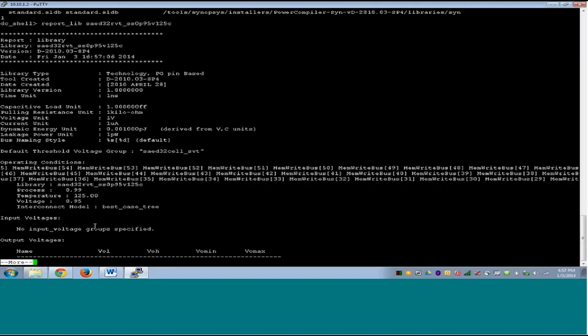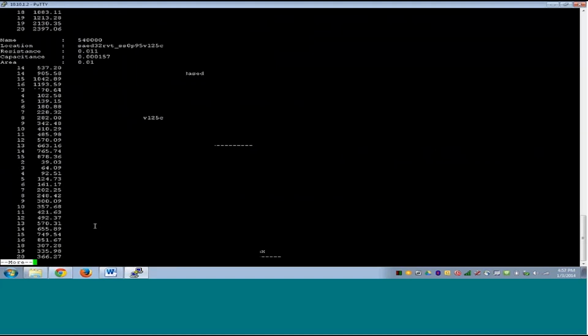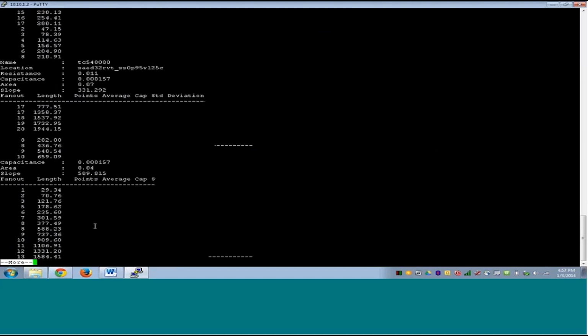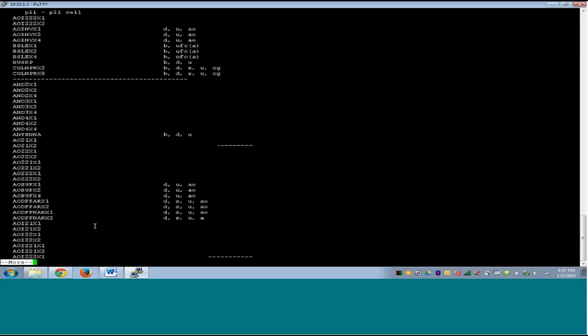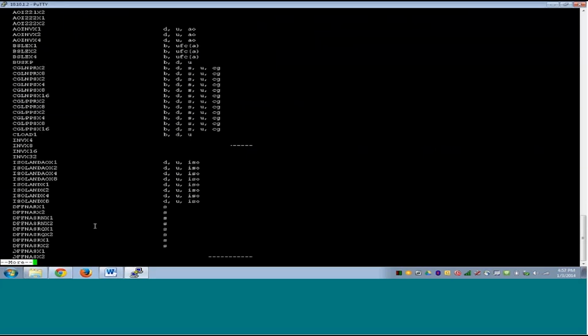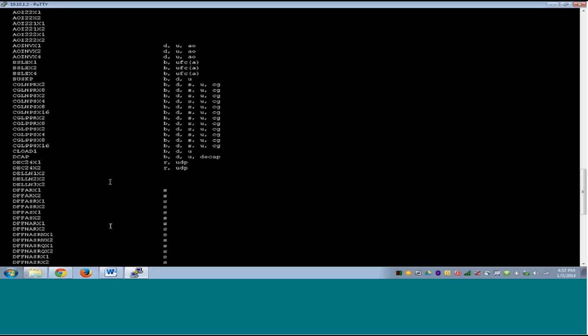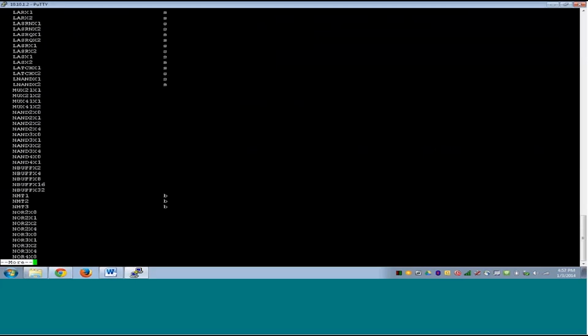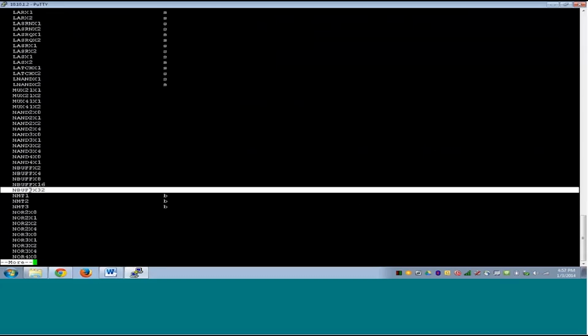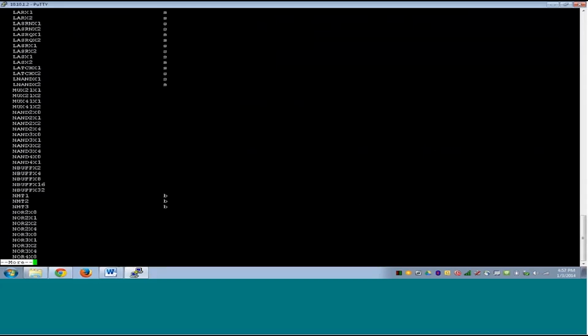So we saw the report list command yesterday. Let's see what all cells are available. Buffers will be starting with either I guess. Oh, B is not there. So yeah, we saw nbuff. So we have nbuff2, nbuff4, nbuff8, nbuff16, nbuff32. By experience, I could say that X16 or X8 drive strength should be good enough. So this is where experience comes in. X32 is a bit large.